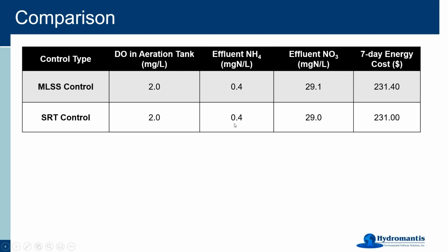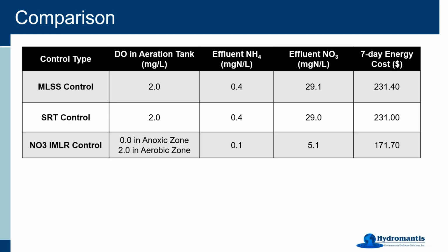Okay, SRT. More or less exactly the same kind of story. As you remember, there were somewhat different dynamics, but in essence, it put the whole system into roughly the same operating point. Now, if I had chosen a different SRT set point, there would be a different story here. Maybe I would make it extra long or extra short, and things would change correspondingly. But for today's example, those two things were more or less pushed into the same operating place.